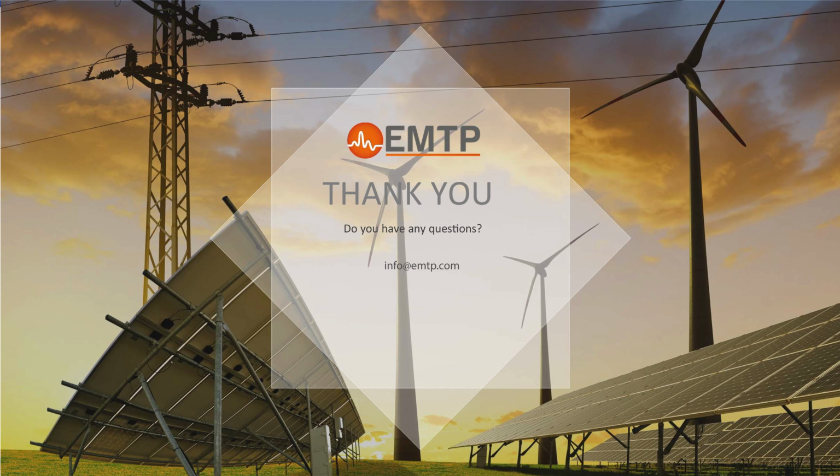If you're talking about the implementation of 59P protection, you need to have PTs on the high side of the transformer, and yes, PTs could increase the cost of that mitigation option. In some cases there already exist PTs on the high side, so you don't need to add PTs. But if they don't exist, then there's an increased cost associated with that.